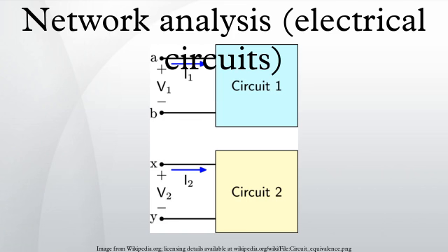Definitions. Equivalent circuits. A useful procedure in network analysis is to simplify the network by reducing the number of components. This can be done by replacing the actual components with other notional components that have the same effect. A particular technique might directly reduce the number of components, for instance by combining impedances in series. On the other hand, it might merely change the form into one in which the components can be reduced in a later operation. For instance, one might transform a voltage generator into a current generator using Norton's theorem in order to be able to later combine the internal resistance of the generator with a parallel impedance load.